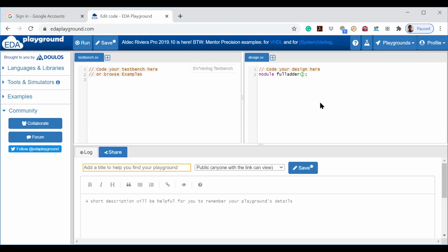You can write it randomly, that is not a problem, but I suggest you follow a uniform pattern. That means always mention output first. So the outputs are sum and CO, and A, B, Ci are the inputs.